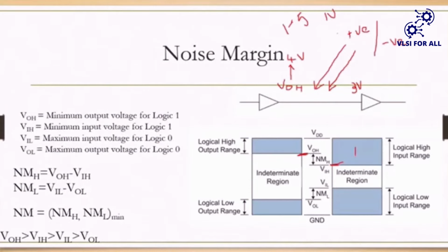Sir, because of negative noise, my value got reduced. It's okay, man. We have your noise margin capability. How much does it have, sir? I have 1.5, sir, so don't worry. Till the noise is beyond 1.5, no problem. The system will detect and recognize your output as it is. As my noise margin is 1.5 volts, the noise occurrence is only 1 volt. So the system can detect 3 volts as a logic 1 only, because this is the minimum.